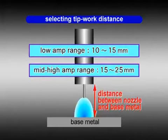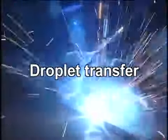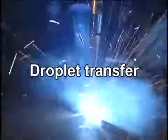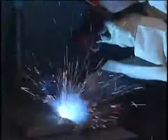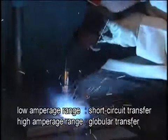Finally, we will explain the influence of the weld metal transfer mode on the weld bead. In CO2 arc welding, the arc transfer mode transitions from short circuit transfer to globular transfer after around 200 amps.